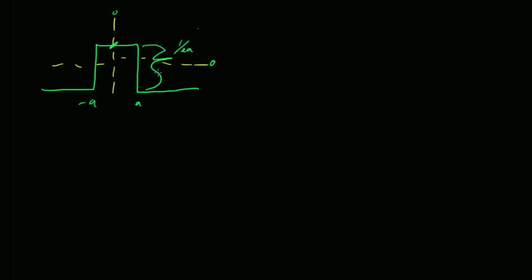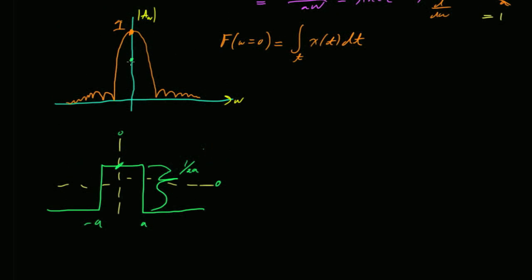Yes? You have to account for it because now you're just looking at the positive area. If you move the entire signal down, you can't integrate it anymore, right? So what you do in that case, if memory serves me correctly, and God knows it may not, is this: if you want to solve for your Fourier transform at omega equals 0, your DC offset, you can't just apply that integral because this thing integrates to negative infinity, right? So in situations like this, you could either shift it up, integrate it, and then shift it down, which is basically how we figured that answer out.